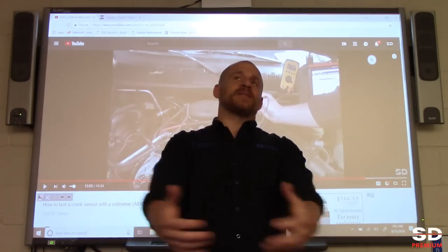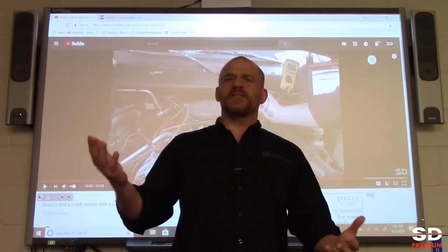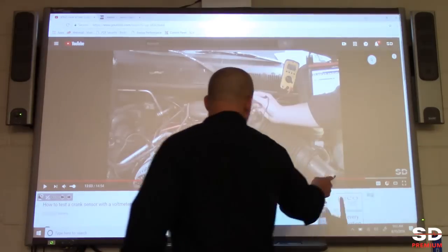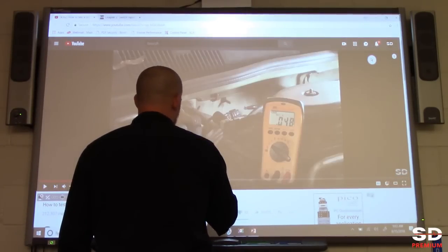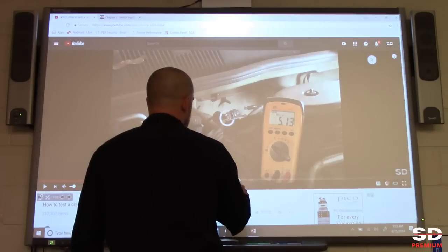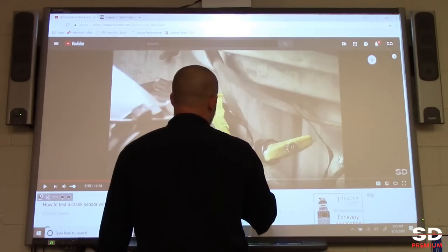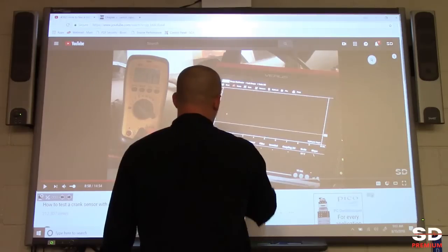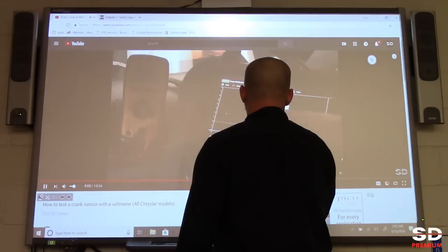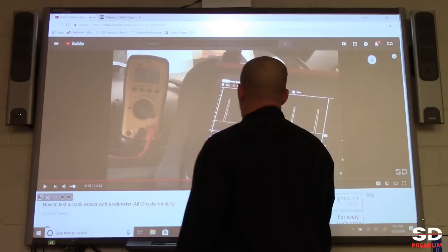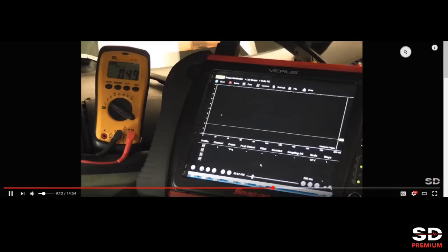This is what we're doing here, some scan data stuff. I'm going to do a bypass test on a system that will not react to anything I do with the crank sensor alone. My timestamp is 13. I want to go back to that picture, and I'll show you why it won't react. The average voltage one that I just showed you guys. This guy right here. Go 200 millis. All right. Okay, right there, hold on. Go ahead and crank it again.